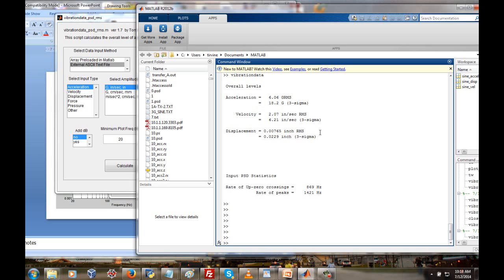And I'm showing the 3 sigma peaks there. Well, put peak in quotation marks. Let's just say the 3 sigma levels for each of those 3 metric types. But please keep in mind that in a shaker test system, as we're actually doing a test, we could get 4 sigma peaks or maybe even 5 sigma peaks.